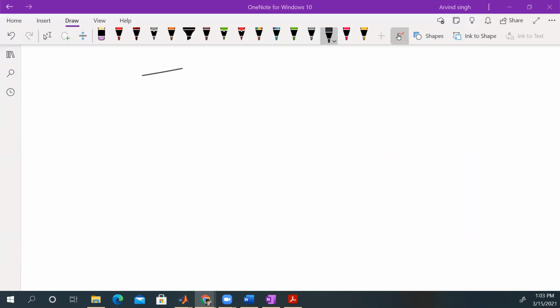So let's see. So we have the induction motor. So we're on the diagram showing the power flow of the induction motor. This is again straight from the notes, you have the input power. And then what happens? We have power going into the motor terminals, then it goes into the stator. So in the stator, you're going to have some losses with the windings. So you're going to have P copper losses in the stator,